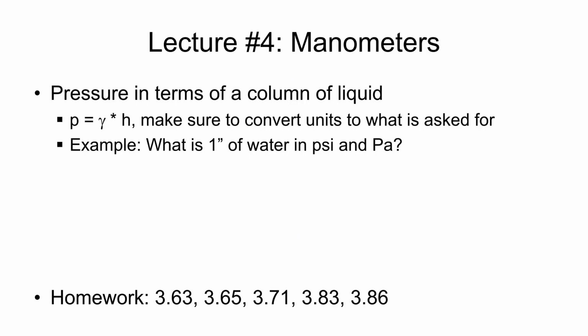As I mentioned with the barometer, it's very common to express pressure in terms of a column of liquid. So with HVAC ductwork, we might talk about how many inches of water pressure the ductwork has, or for something like a barometer, you might hear us say how many inches of mercury or millimeters of mercury the atmospheric pressure is at. That's another common way to express pressure. But again, we can still use that height to calculate an actual pressure in PSI or Pascal.